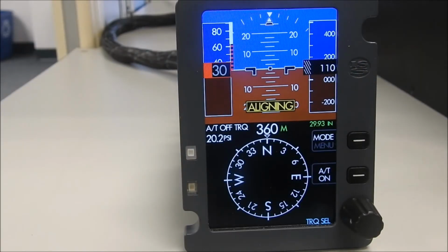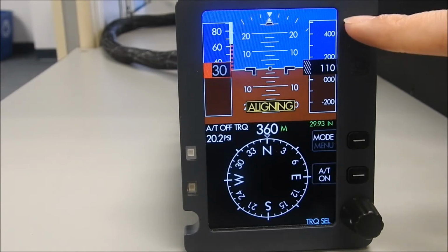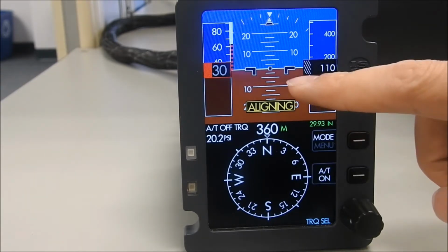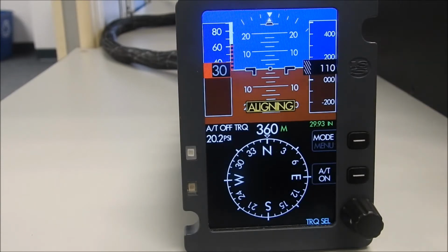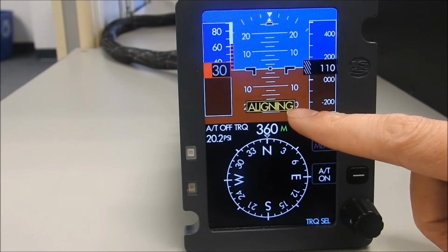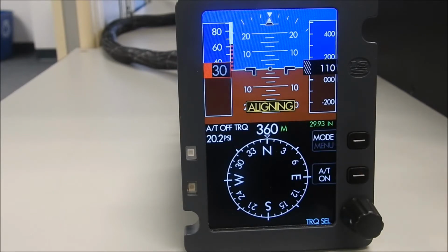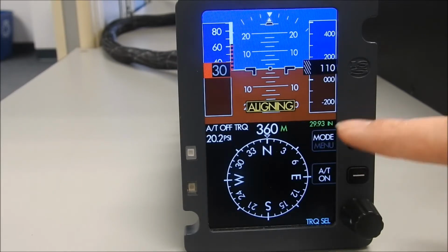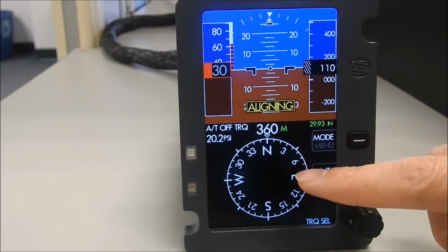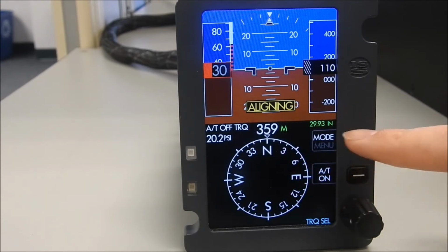Hello, and welcome to the operational overview of the integrated standby unit with Autothrottle by Innovative Solutions and Support. The main display acts as a standby reference for airspeed, altitude, and attitude throughout flight. On power-up, it will perform an alignment for about 1.5 minutes. The bottom half includes heading reference, a compass, and the Autothrottle interface displayed here and here.